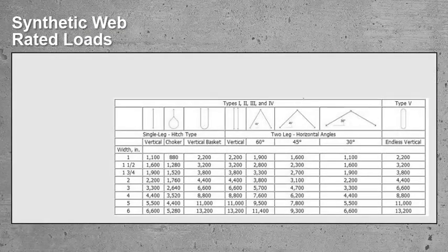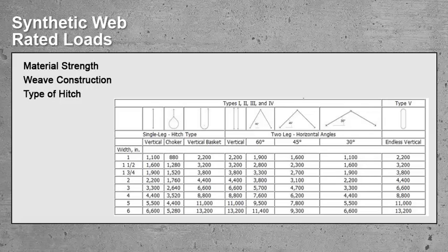Rated loads for synthetic web slings are based on material strength, weave construction, type of hitch being used, and the angle of loading. OSHA provides a chart for rated loads, but please consult the manufacturer or qualified person for lifts outside the provided chart.